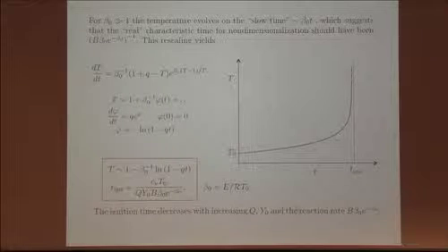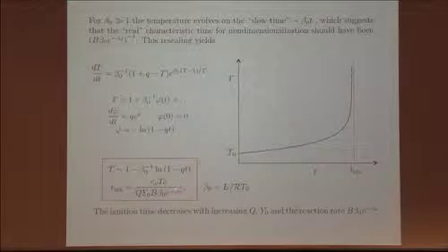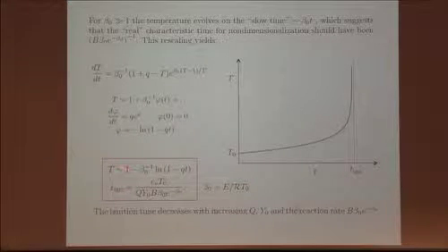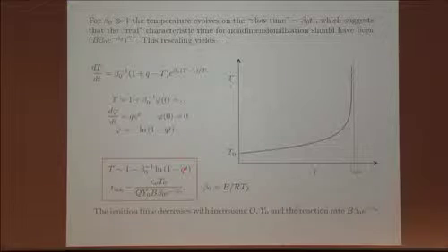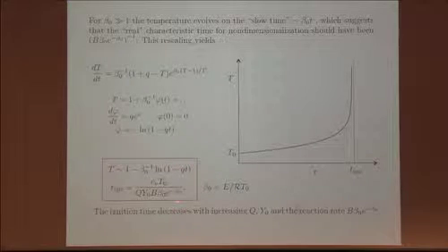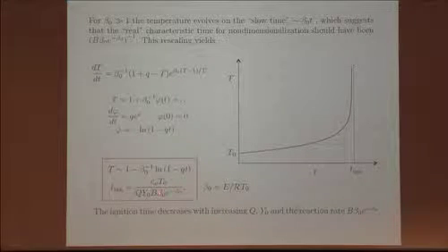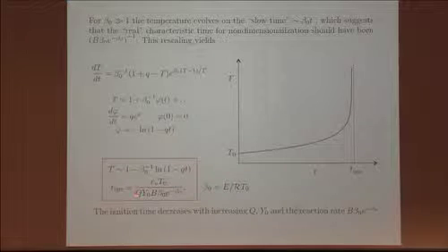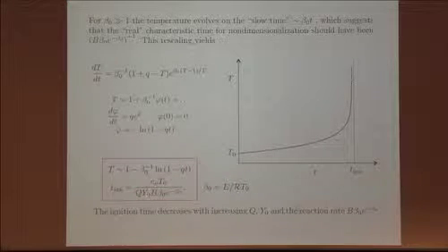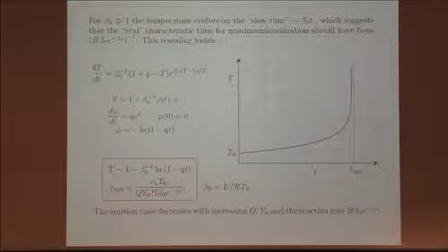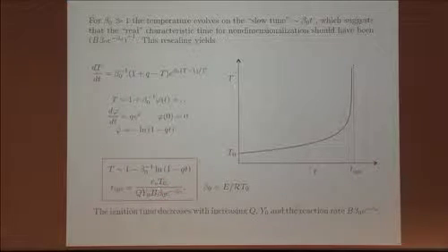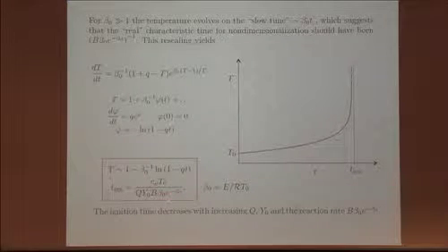Okay, so this is the determination of the ignition time, and now we can recast this t equal to 1 over q into dimensional form, and in dimensional form we get a very clear dependence on all the physical parameters. In particular, we see that it's inversely proportional to q, or y naught, and to the reaction time, b beta e to the minus beta naught. So the ignition time is the reciprocal of that.